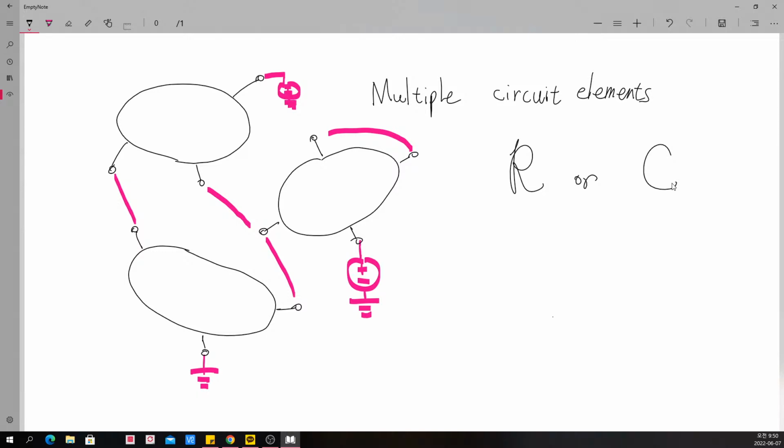Please try this: you have already done your DC simulation with a certain MOSFET, so I recommend you first introduce a resistor and connect it to your transistor's drain terminal, change the gate voltage, and measure the change of your drain voltage.